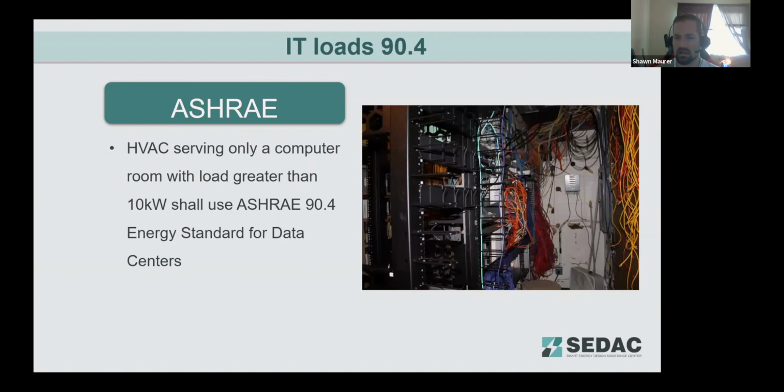IT loads, ASHRAE has a standard for data centers, 90.4. But HVAC serving only a computer room with a load greater than 10 kilowatts shall use that standard for its design. So that's what's being referred to here.